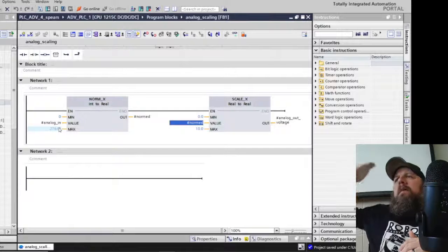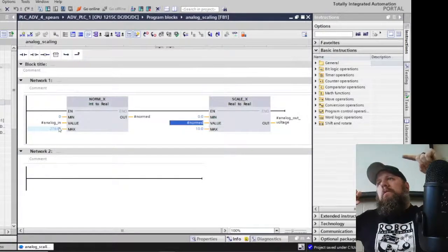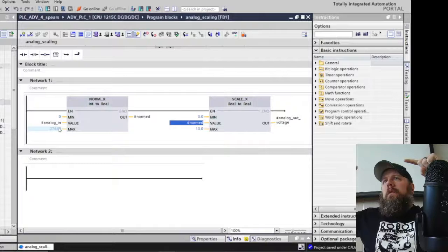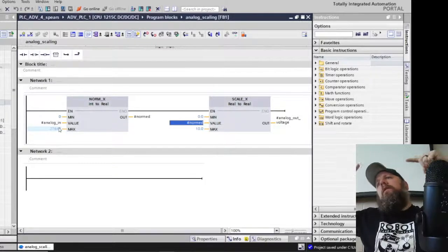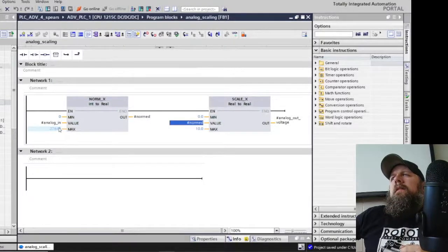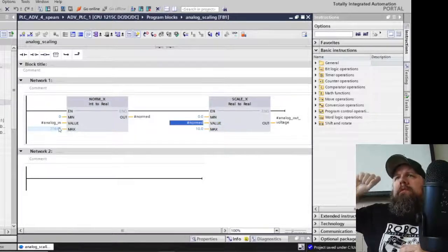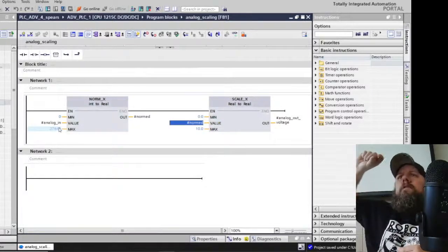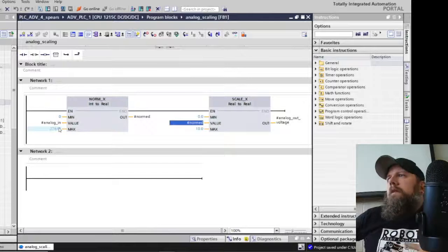I can put a timer on a counter and I could compare a voltage that I know to a voltage that I don't know, and I can just keep pushing up that voltage until it equals. And that's in general what we're talking about. It zooms up real quick and then it matches the voltage, and then boom, it knows what the voltage is.